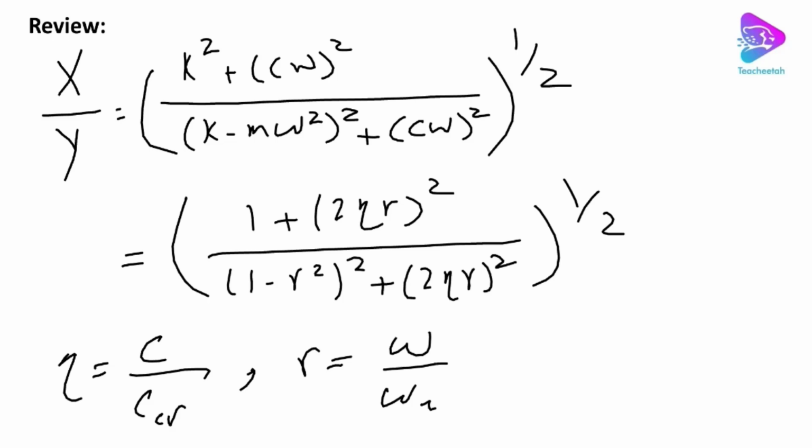So eventually when you have x, you can find the particular response of the system, which is basically x sine omega t minus phi, and we have phi before. So keep that in mind, because you're going to see that in future problems. For example, the amplitude of the base is given and the amplitude of the actual system needs to be calculated, or in some cases you need to find the allowable amplitude of the base to give you a limited amount of amplitude of vibration for your main system.